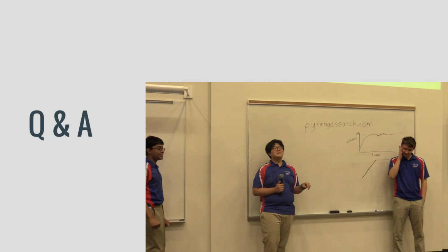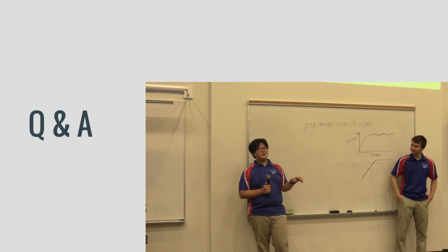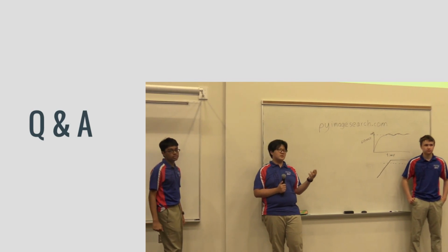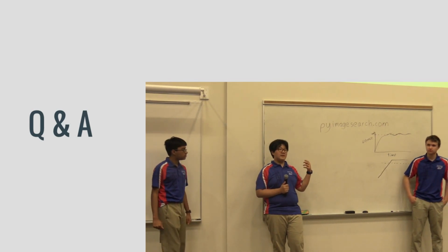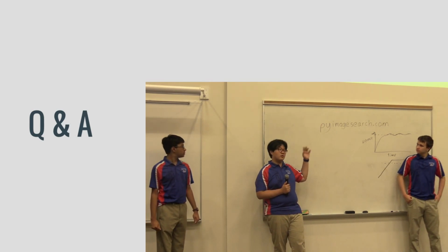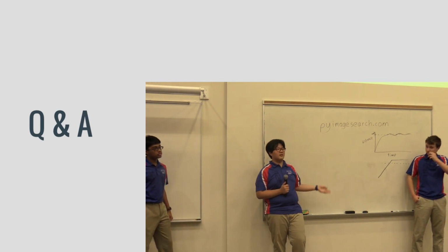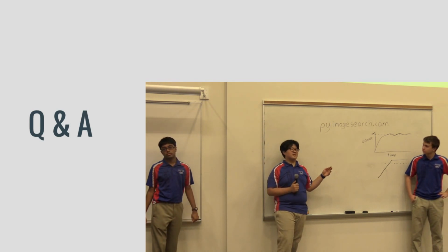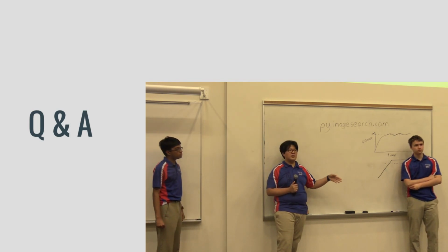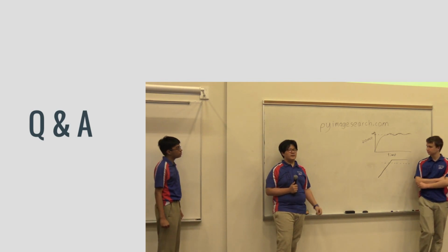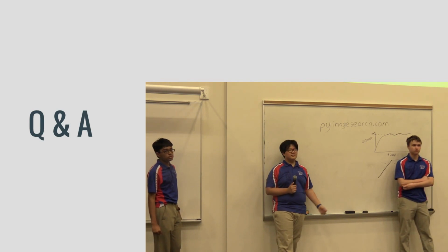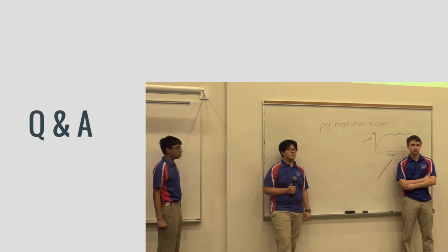Okay, yeah, math. So that was our equation, and from there we can basically predict what our shots were going to be like. We would have that inside the Python code on the Raspberry Pi, and we would feed the coordinates into that equation and hopefully get the correct offsets out. But sometimes those equations don't necessarily work. So if it was a linear equation, we would tune the y-intercept or the slope to fiddle with it a little, especially if the camera gets moved, then we have to redo everything. So those were the general tuning steps that we took.